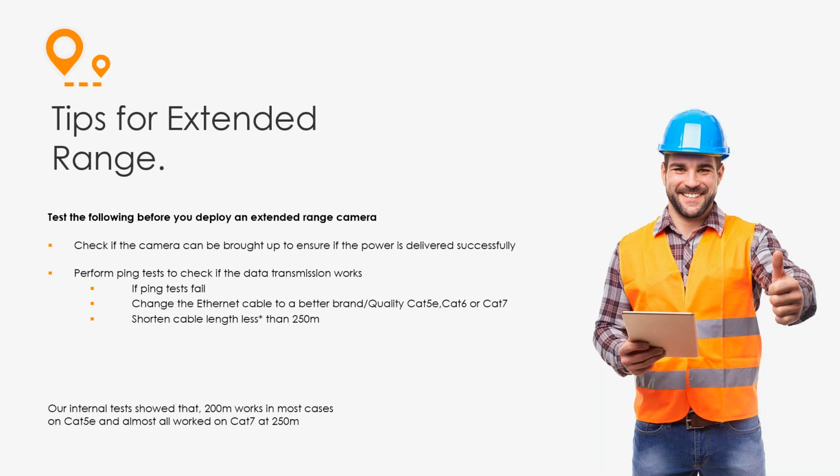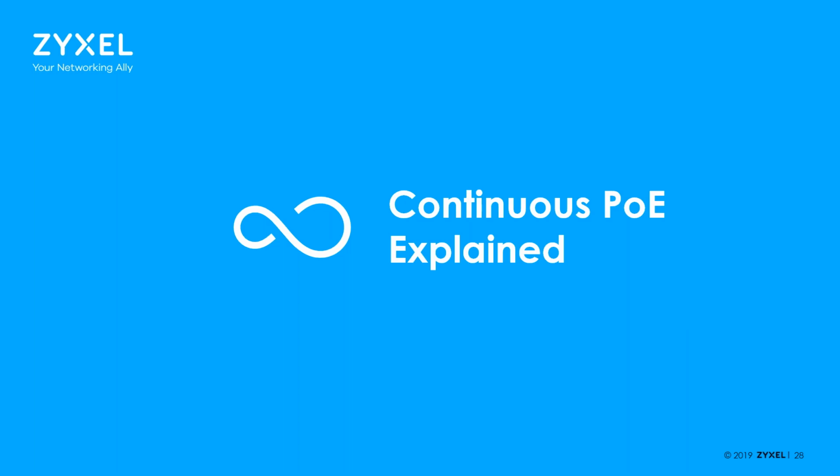There are quite a few things you can actually do to improve this. One, a better brand of cable, better shielding of the cable, or a better category cable. So if you have a Cat5e cable, you might go to Cat6 or Cat7 cable and get it working that way. Or shorten the cable length, which is usually a bit difficult to do because the camera is in a fixed position and the switch is in a fixed position. So in some cases maybe, but usually quite difficult, to find a better cabling route or a shorter cabling route. But those are the things you can do.